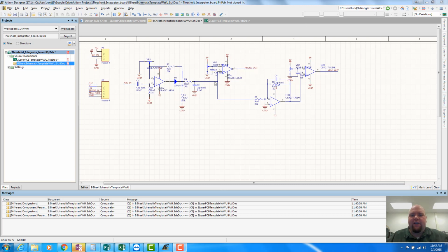So we also have that signal though, so now this is the rectified sinusoid, which has been low-pass filtered, so it should kind of be just sort of a DC with ripple, where the magnitude of the DC corresponds to the amplitude of the AC. That then runs through this circuit here. This circuit here is an integrator. So we have an integrator, it's a leaky integrator here.